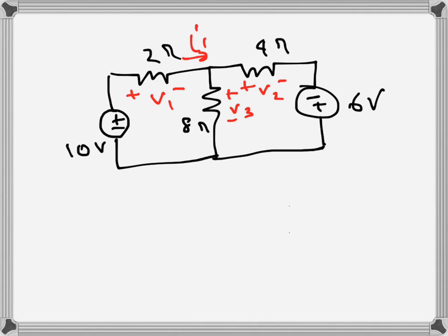For this circuit we need to find the three voltages V1, V2, V3 and this current I1. Now when we look at the circuit we can see that this is a node here, so we will write KCL for that node. So we will assign two more currents, one is here I2 and one is downwards. These three branches are connected to this node, and we can say that this node's voltage is V, just V.